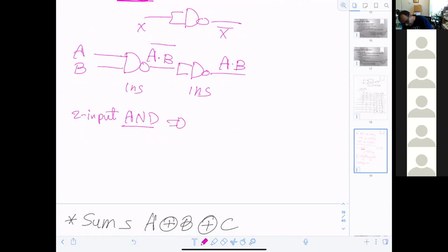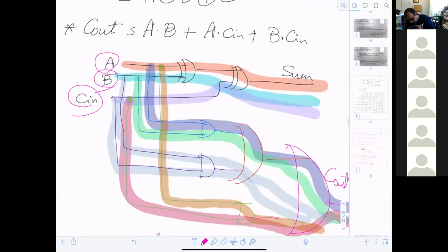Anyway, so it's going to be 2 nanosecond. Sounds good? Is that for AND or NAND, the 1 nanosecond? I use the NAND gate to help me bring the AND gate. Oh, okay, I got what you mean. So the AND gate is 2 nanosecond. Yes, because I know the NAND gate is 1 nanosecond. So I can go here in this circuit, and I say here 2 nanosecond, 2 nanosecond, 2 nanosecond.